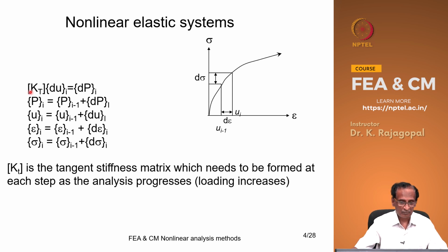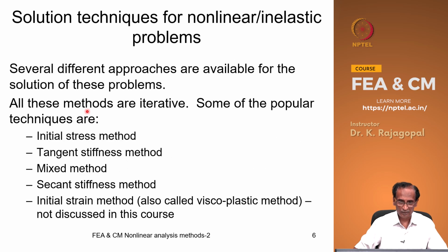Okay. And in all these problems our stiffness matrix needs to be updated every iteration. Then once we update, we have to assemble, and then we have to triangulate, like we have to make it an upper triangular matrix and so on. So these analyses take a lot of time, and actually this is one simple method, but we can improvise this, and that is shown here.